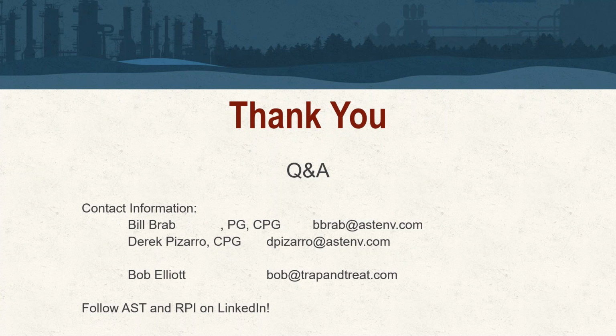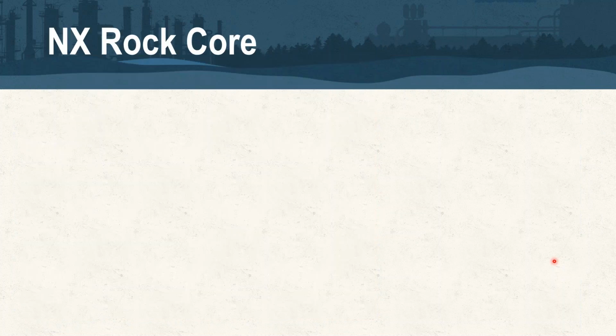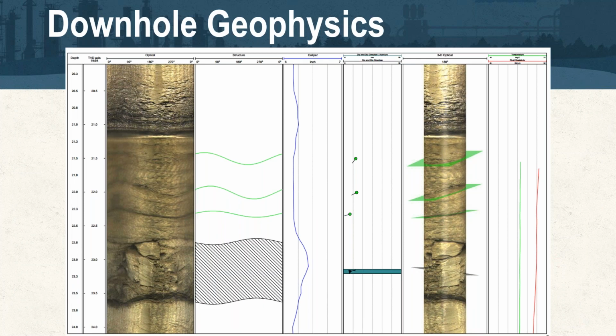I have the ability to back it up here, I think. This example here that Bill used, the resolution on some of these tools these days, whether it's an optical or an actual tool like a caliper, you've got great detail, and to skip one of these tools really isn't going to save you a lot of time or money on site. Usually if you're trying to save costs on geophysics, and I don't recommend that personally because these suites are pretty comprehensive, we see clients or subcontractors try to cut out OTV or ATV, or maybe skip the heat pulse flow meter.